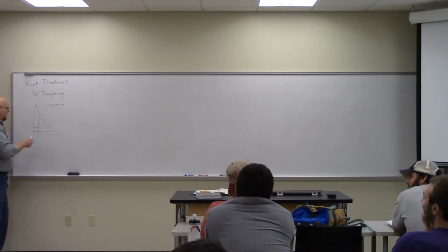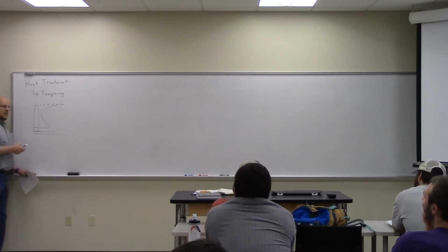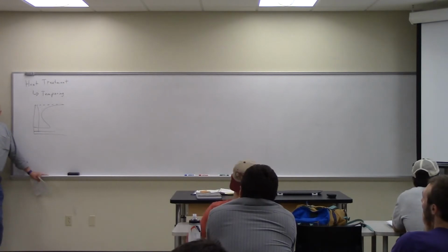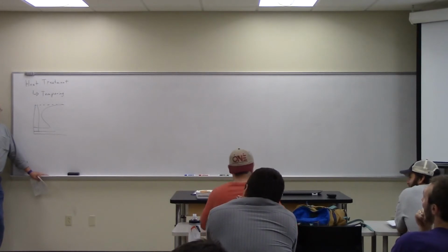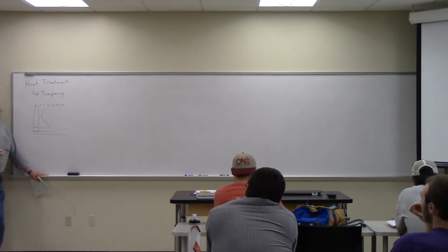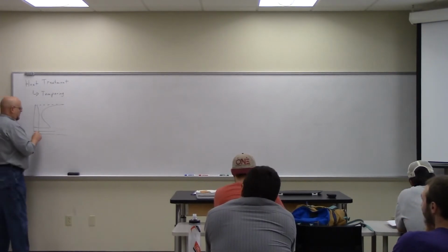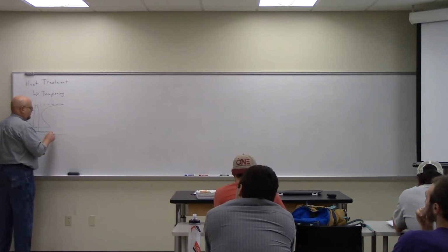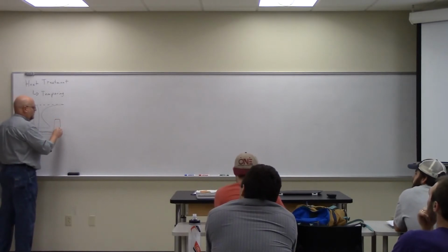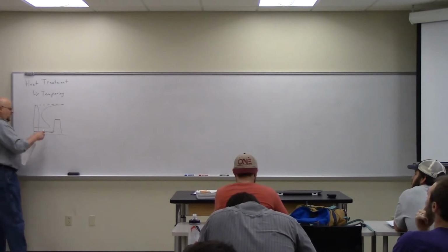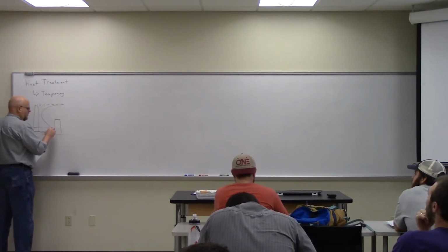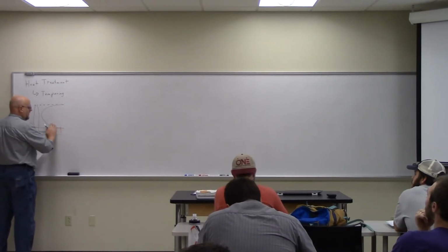Anyway, this stuff down here is really brittle. The martensite is really brittle. If I really have quenched it down to that condition, it won't bend much. Pure martensite won't bend much. It's a very brittle material. So what I want to do is bring it up, heat it a little bit, and bring it back down. So I heat it up above the martensitic start temperature. Probably don't even have to heat it that far, honestly.